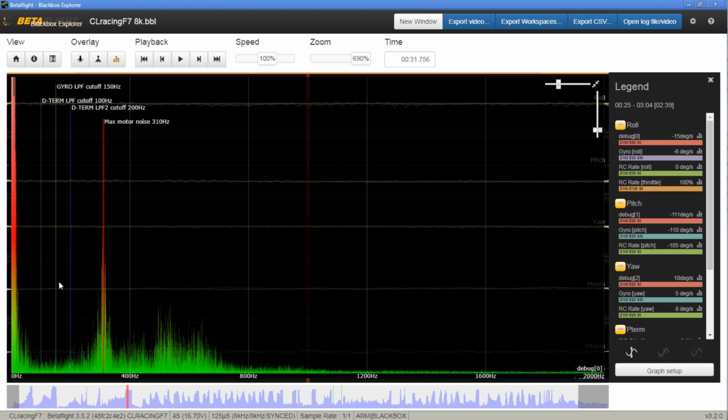So what should you have going into this? If you can run a log, you can look at this on your quad, and I don't know how you would do this without a log. So for FlightOne, you do have the option to flash to Betaflight, run some logs on your filtering to get an idea of the machine, your raw base noise and stuff, and then flash back to FlightOne to set some stuff up. So that's an option. It's kind of a pain. You could do that. Obviously, if you're in Betaflight, you can look at this, or just get an idea of my recommendations here.